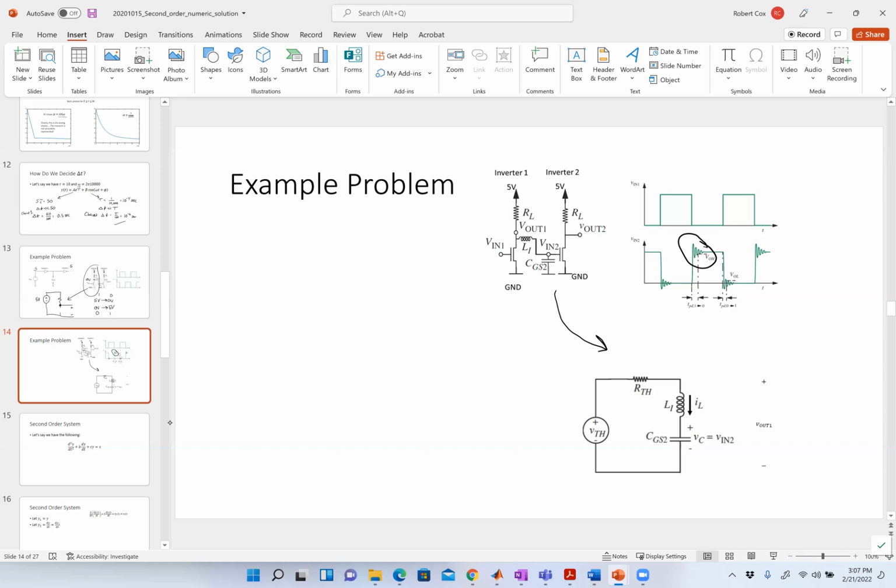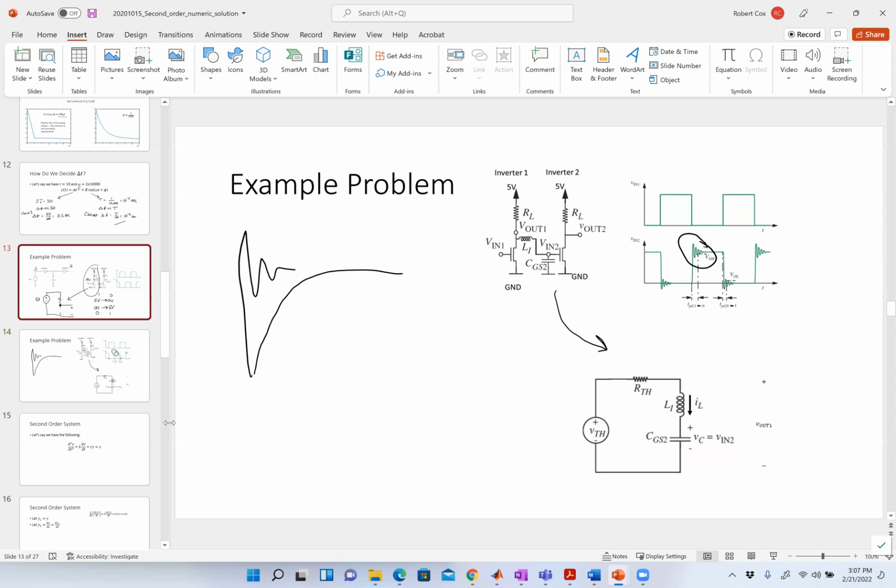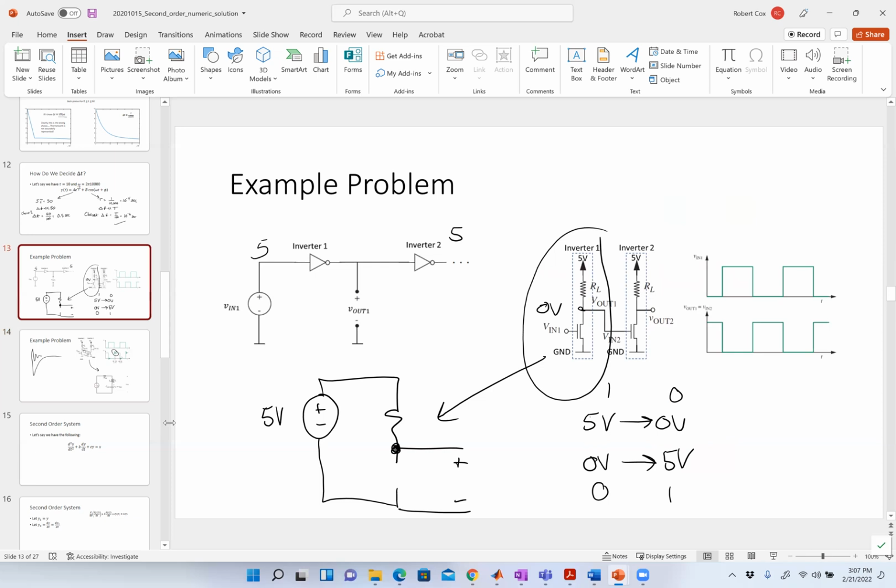All right. Underdamped stuff responds very fast, but very wildly, right? In other words, it shoots up very fast like this, but it overshoots. Okay. If I put a lot of resistance in there, it's going to slow down, but it's going to look like that. All right. So I don't have the wild behavior, but I also made it slower, and that might be problematic too. Because in a digital system like this, what I'm trying to do is get something to go. So I've got a couple of gates in series with each other, right?